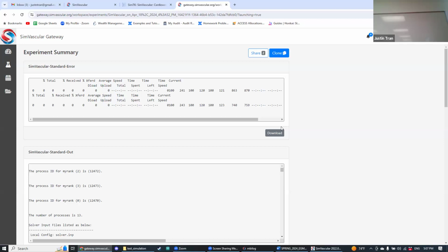I would verify to make sure these vessels are the ones causing the issue. In the worst case, I've told people to do one vessel at a time. Make it one model, just one vessel, mesh it, and if that works, then add another one to it. It's a tedious process, but sometimes that's the most reliable. Visually, wherever you see pinching, that's the issue. There's that one, and this one, so I would look at those and see.